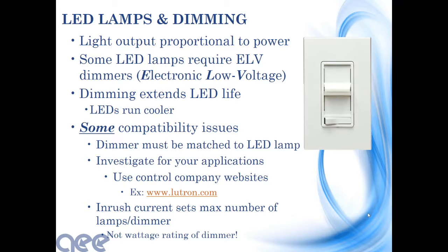So you can go to control company websites like the Lutron website and find tables of compatible dimmers, ones that have been tested with LEDs.